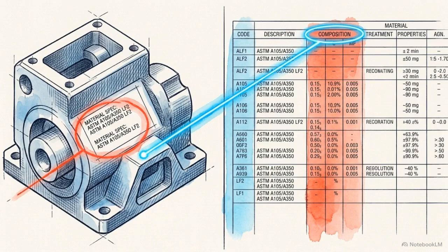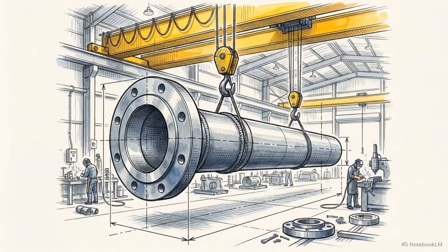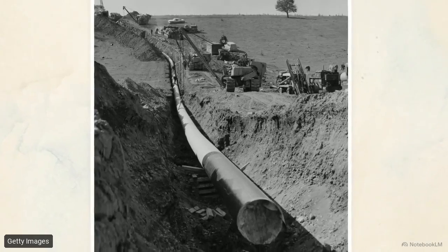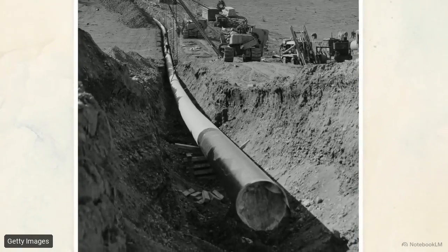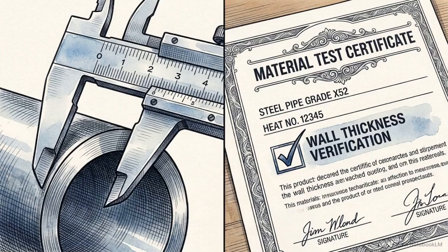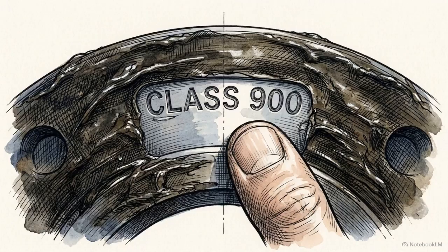When an isometric drawing lists a pipe class, it points to this specific pre-calculated PMS bundle, providing a single reference for the entire assembly's material requirements. This specification dictates exactly how millions of dollars of steel will be physically assembled and laid into the earth. This creates a dual responsibility for QA/QC teams. They must verify the actual wall thickness on the material test certificate against the required pipe schedule, and they must independently verify the physical stamp on the flange to ensure it meets the pressure class.